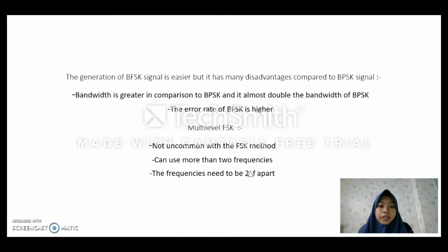Disadvantages of binary frequency shift keying. The generation of a BFSK signal is easier, but it has many disadvantages compared to a BPSK signal. Firstly, its bandwidth is greater compared to BPSK; it is almost double the bandwidth of BPSK. Secondly, the error rate of BFSK is higher.